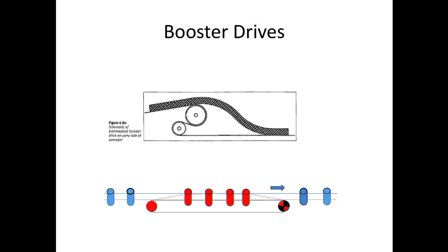Okay, look, this is a way, if you've got a really long belt, you kind of think, how on earth can I actually get some more power into it? Because it's one of those things where you don't want to keep bringing up T1, if you can actually put some power in halfway along. So here, this is a good way of getting the material coming over, so you just bring it up and back. But see what's happening though, this pulley here is working on a dirty belt, and so that's when you probably need a slatted one. And then there's a bit of fall here.